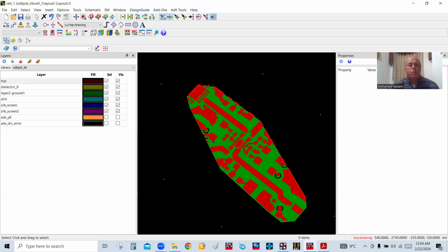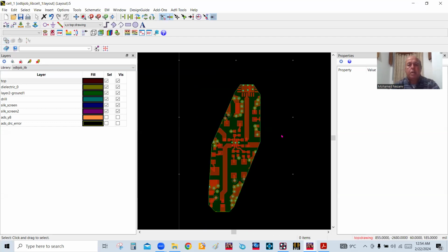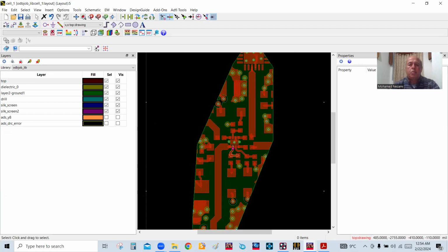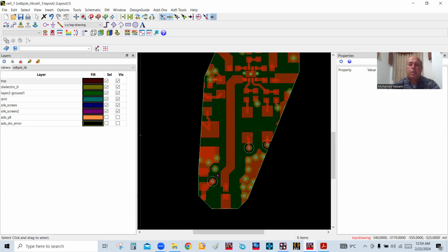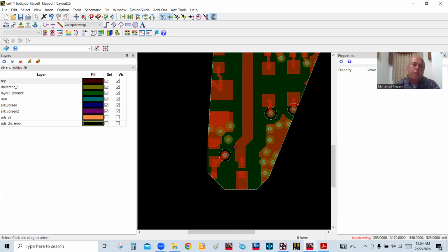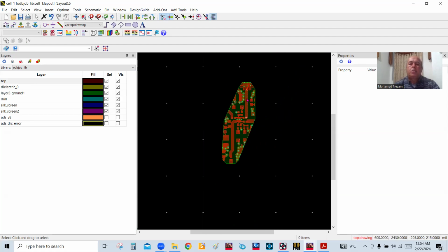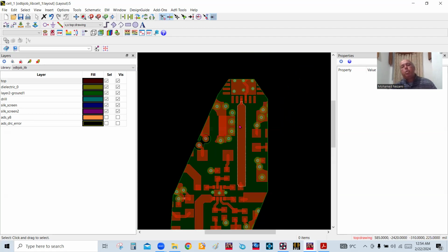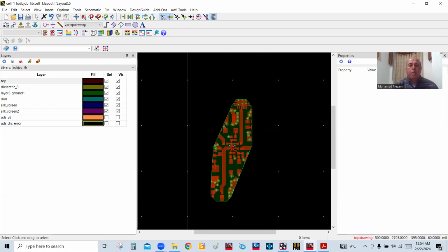What we're trying to do is look at the return loss and the insertion loss, to see if there are any issues due to the fact that this is so close to this. The reason we want to do this is because you might get a suck out or a notch in the frequency response that is really not very far from the band of operation. So we want to make sure that that's not going to happen.